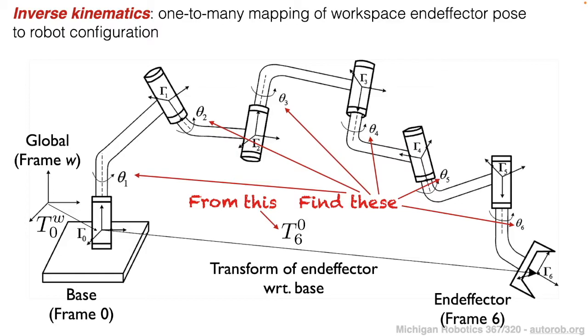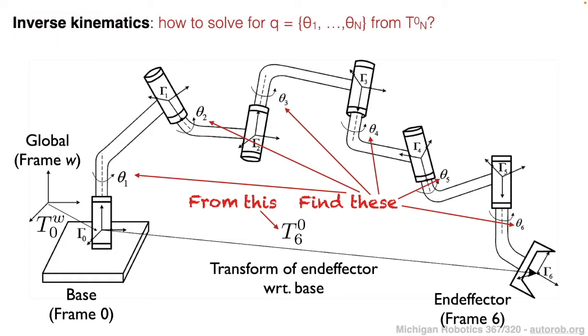But that alone does not allow our robot to actuate that task, to actually produce some control policy to move the end effector to pick up that object or to open the cabinet. Just like for our PID controller, we need to express the desired angle or the desired prismatic translation of each of these joints. That's the purpose of inverse kinematics. Inverse kinematics is going to allow us to solve for these joint configurations based on this desired pose of the end effector.